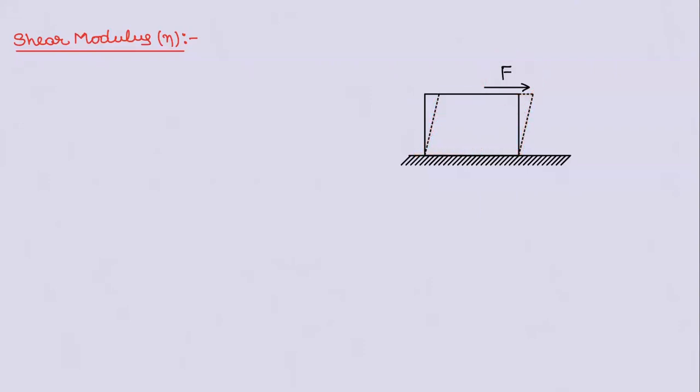This shearing is measured in this way. This angle theta is the shear strain. But anyway, you know very well, this is a small triangle. For a small angle, sine theta is nearly equal to tan theta, which is equal to theta. You can use shear strain as theta, or you can use the change in length delta x, and this perpendicular length is L.